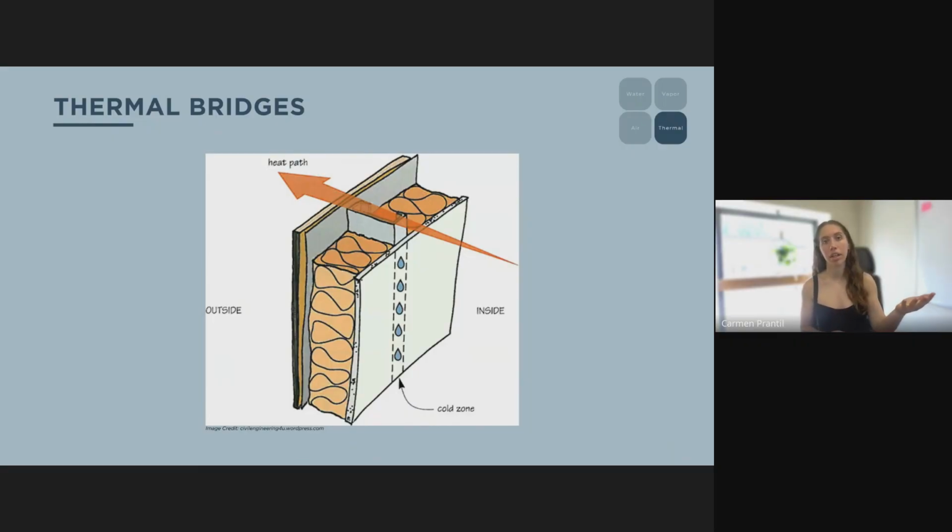Because when you install that exterior insulation, all of a sudden your steel stud's not cutting through it. So when we see steel studs without the exterior insulation, that's a thermal bridge. Window frames or edges. So maybe you felt a freezing cold window frame from the inside in the winter before, but everything else is completely fine, but the window frame is freezing cold. Also balcony projections. Typically these are concrete slabs that are literally cutting through the building envelope.